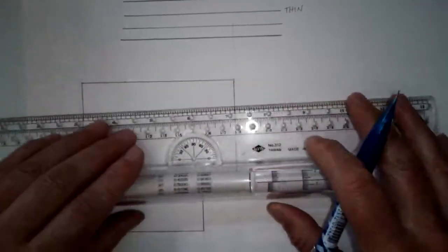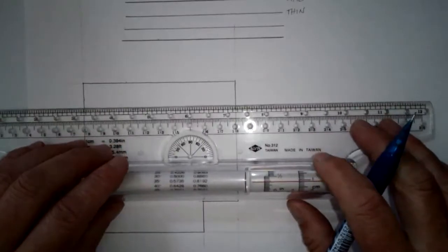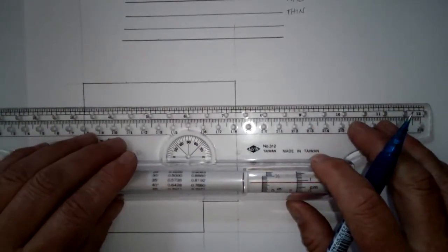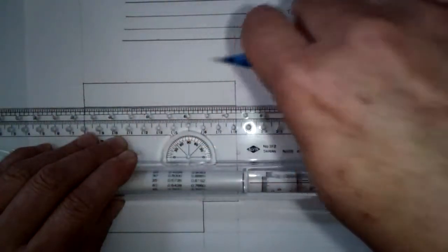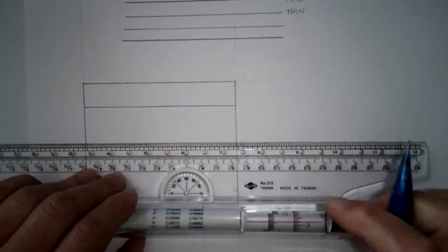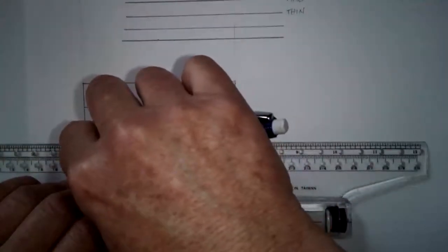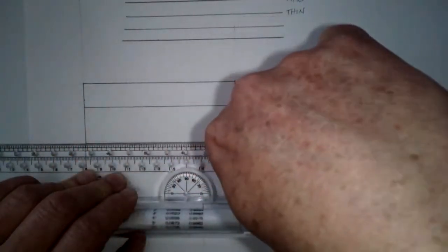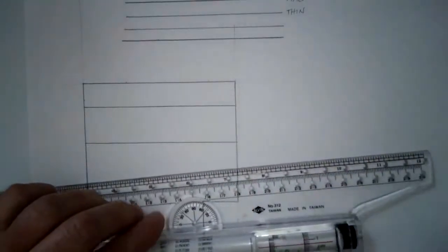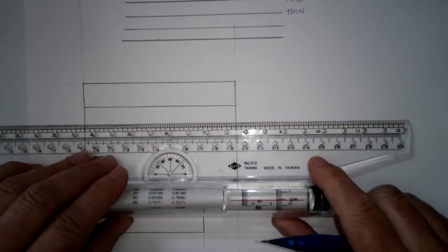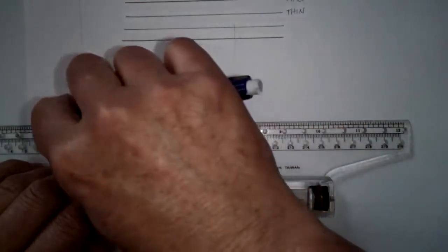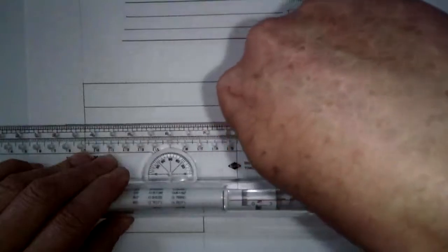So to create a thin line, that's a hidden line, for instance, I'm not going to bother with the pattern. I'm going to first of all draw that line out as a continuous line, and I'll do that in two spots. We'll pretend we're looking at a hole from the side. And then I'm also going to draw in the center of this a center line. I'm not worried about the line pattern yet. I'm just drawing where those lines belong.